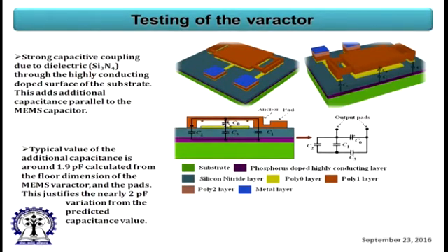You are interested only in the capacitance between the top and the bottom electrode, yes or no? This is the capacitance for the varactor. Now, you see in the path there is a dielectric capacitance C2, there is also another capacitance C3, and there is another one, C1.